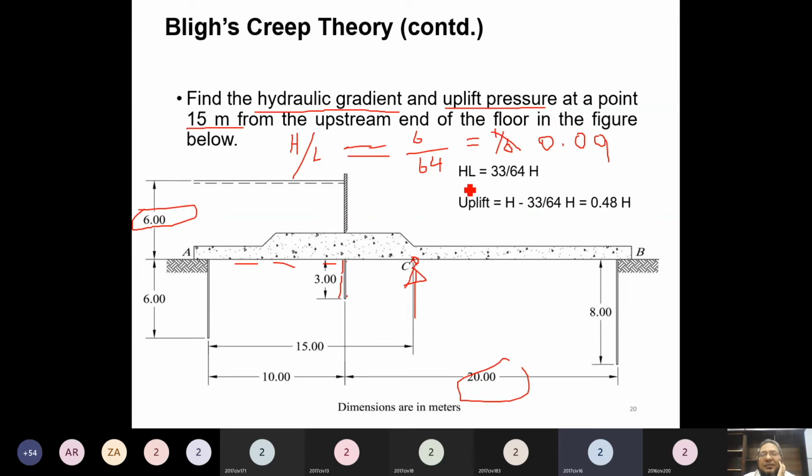तो वो अब आप निकालें जी. और this divided by that into the head would be the head loss up to point C. ये head loss आया point C पे. तो point C पे देखें ये कितनी लेंथ है? ये 6 + 6 12 + 10 कितना हो गया? 22 + 6 28 और जमा ये 5. ये 5 ही बनता है ना? हैं? Yes sir. So this is 33.